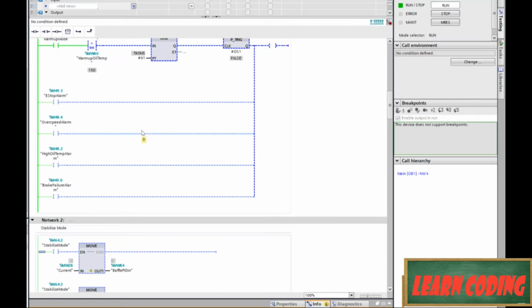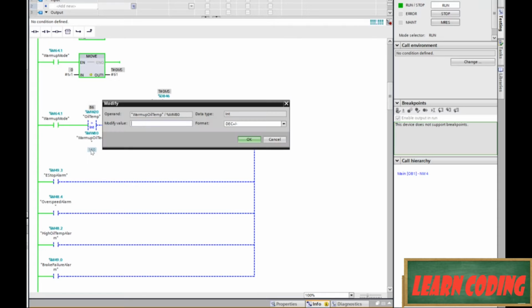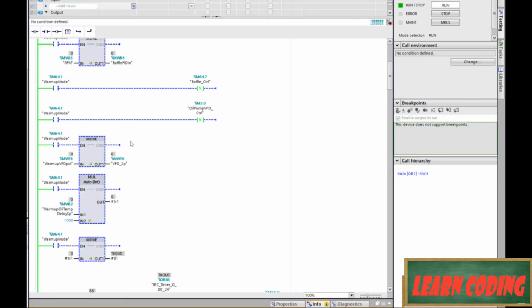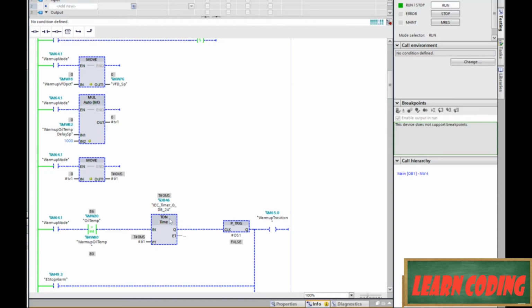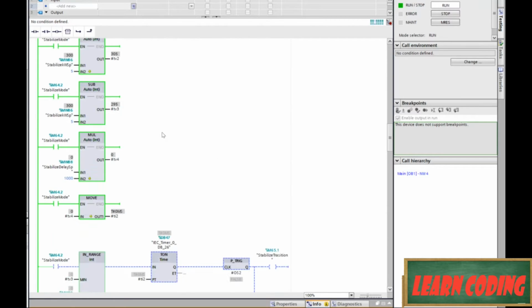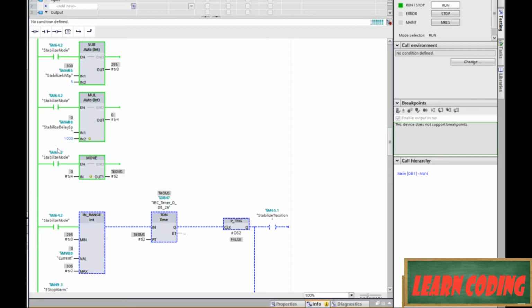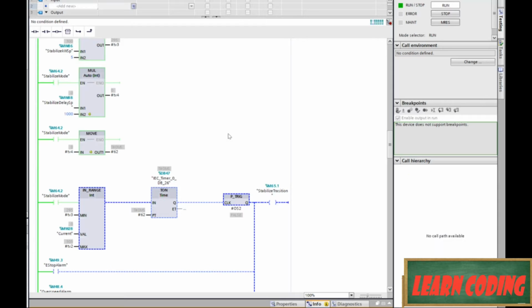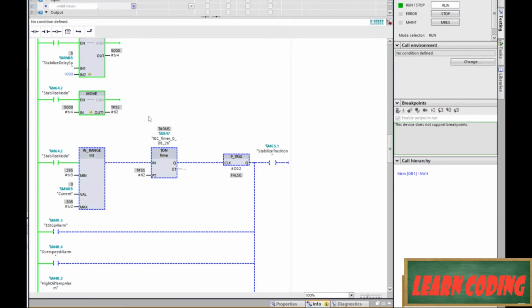Okay, so now once we get down there, we shouldn't just bounce immediately into the next step. So we're in warm-up mode, and now let's drop our desired oil temperature down to 80. So now we should start timing and time our way out of here. And actually we didn't have a time value, so we jumped immediately, right? Yeah, we have a 0-second timer, so not a big deal if we don't test that guy. And we're down here into stabilize now. And since we're using the same timer logic all the way across, if I go ahead and set this here, I think it's going to be just as good as testing the one up top because it's the same logic.